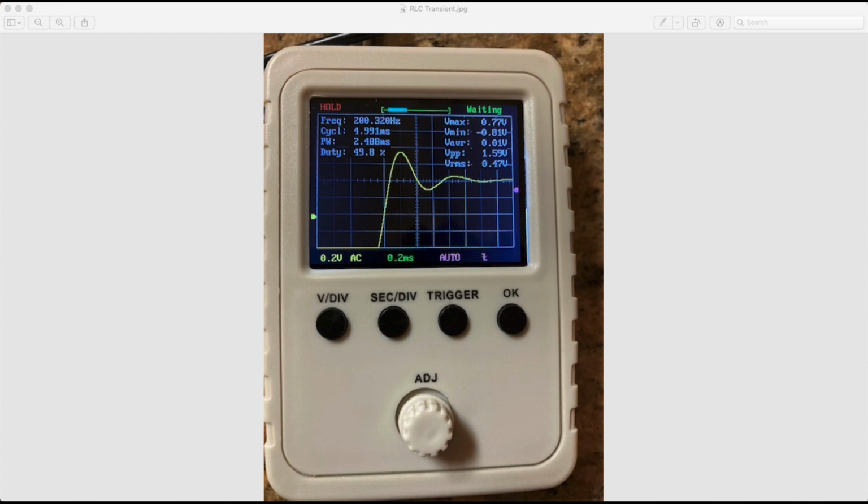If you can actually adjust the potentiometer so you set it to 25 ohms across the middle terminal and one of the end terminals, you can get this to work. But that potentiometer is so coarse, it's only one turn. It's really hard. It goes from 0 to 1,000 ohms very quickly. So yeah, if you set up the RLC circuit with around 25 ohms and the inductor you're given, you can probably observe it.